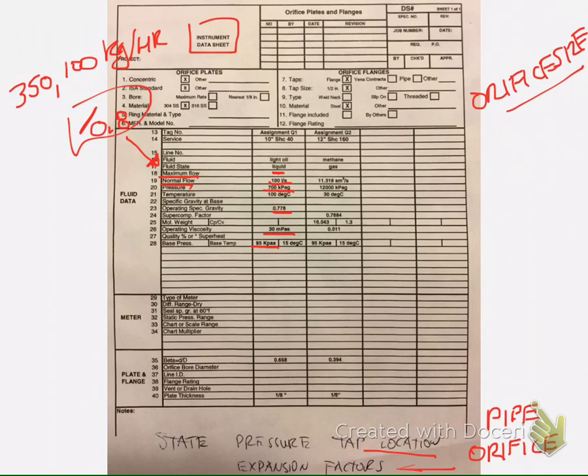I've changed mine already. It says Pascal seconds, and that value that's given to us is in millipascal, so we need to enter 30 and then divide by 1,000, because 1 millipascal second is 1,000th of a Pascal second, so 30 divided by 1,000, and it gives us a DP max of 26.5. So my first output is DP equals 26.5 kPa. So we need to select a standard range, like we pointed out on that procedure sheet.